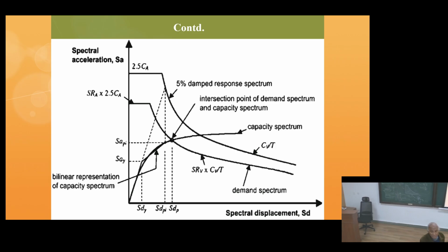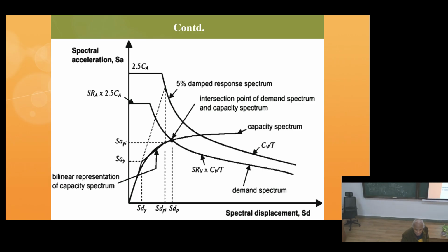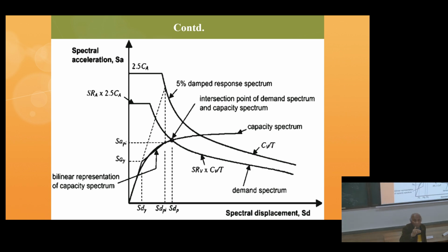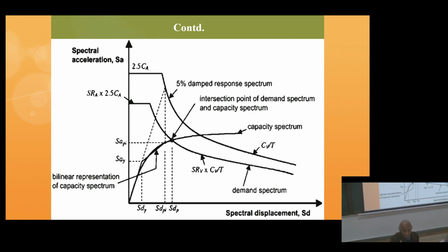But if you say that no, it will remain in the IO to LS range, that means under that bending moment, shear force combinations, the structure has gone into an inelastic state, but that inelastic state is not very highly significant.